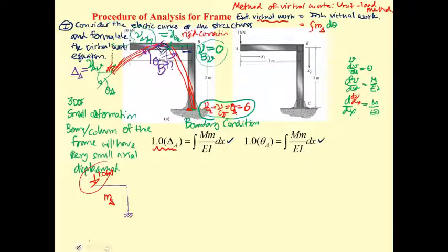And what we have is the d theta. This is going to be d theta equal to M over EI dx. And then you put this, M over EI dx. You get this portion by putting this m sub delta, which is the moment due to the unit load over here, used to determine the v sub A in the vertical direction, or delta A.